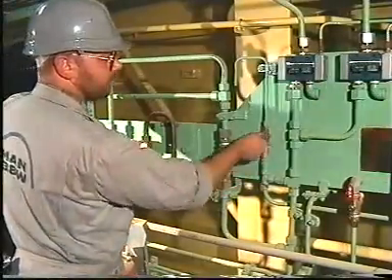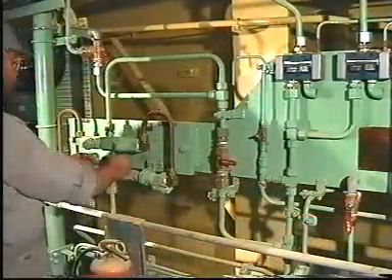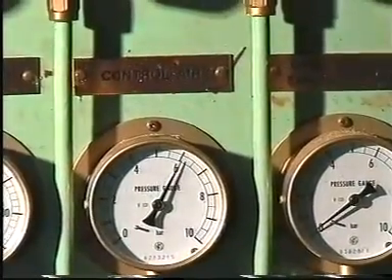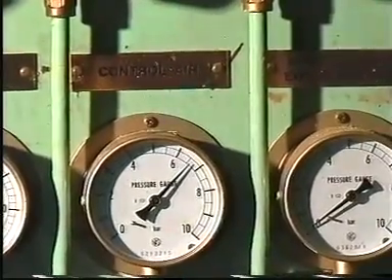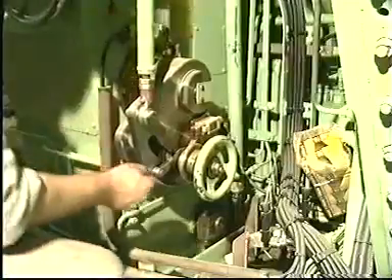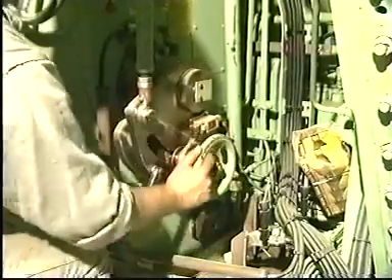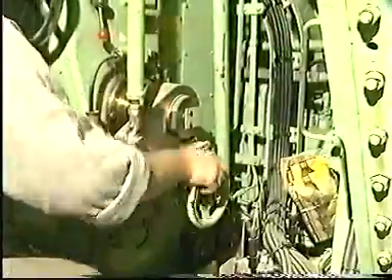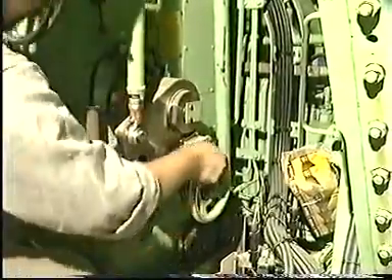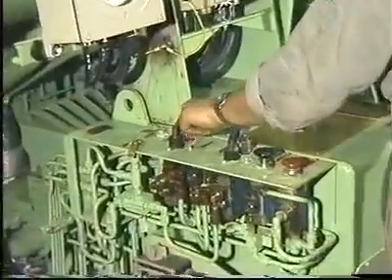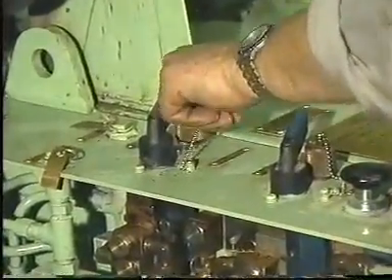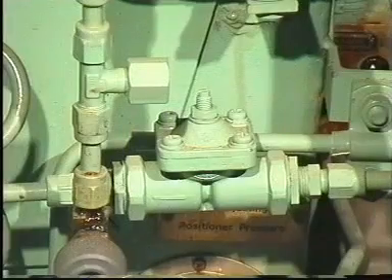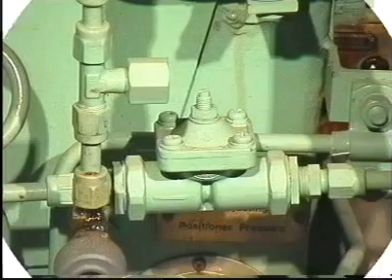Supply 7 bar control air pressure to the pneumatic components on the engine side console. Switch control from the engine room to the engine side console. Turn the regulating hand wheel until the tapered slots of the two levers are aligned. The throttle non-return valve must be fully open before adjusting the VIT system.